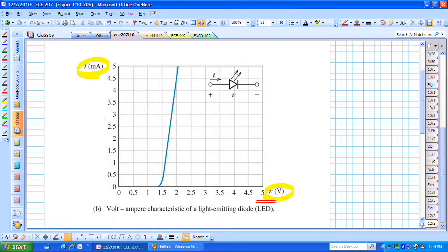If I now look at trying to intersect those 2 points, I started with a voltage of 0 and a current of 4, and now I want to connect that point with a straight line to this point that is at V equal 5 and 2 milliamps, and that's now my load line associated with that Thevenin equivalent circuit. I now have determined what my current voltage relationship needs to be, if I wanted to try to get that a little bit more accurate.